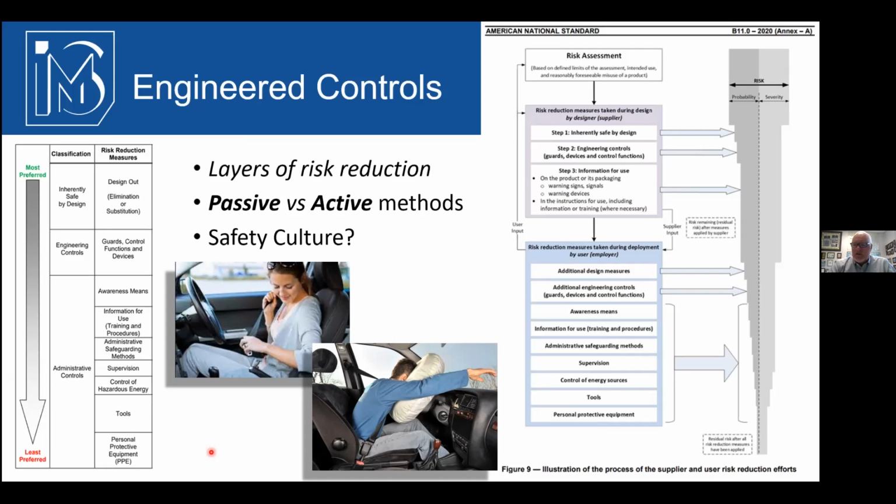So this is where we're going to talk about passive methods versus the active methods we covered before in this realm of safety. This is similar to seatbelts, like lockout, tagout. It takes a human to actually do that, click it or tick it. So anyway, seatbelts and airbags in this case are just as effective, but one relies on a human performing versus the machine performing automatically, as in the case with airbags. So what we're going to talk about basically is, I'll say, airbags for machinery, things where the machine does the thinking and automatically responds to a scenario to reduce risk.